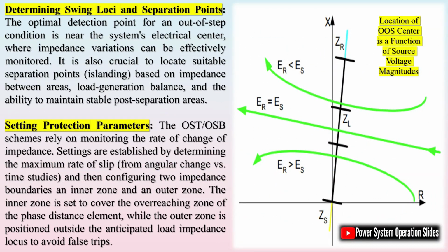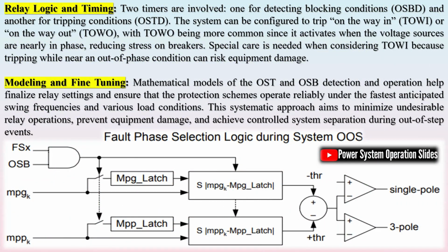Out-of-step tripping and blocking functions: application and coordination. The practical application of OST and OSB functions involves pre-selected disconnect points. System operators determine strategic network locations where controlled isolation can minimize damage. Complementary operation: OST is activated in cases where the generator's swing exceeds stability margins. In parallel, OSB functions block actions by relay elements that could trigger unintended separations in other parts of the network.